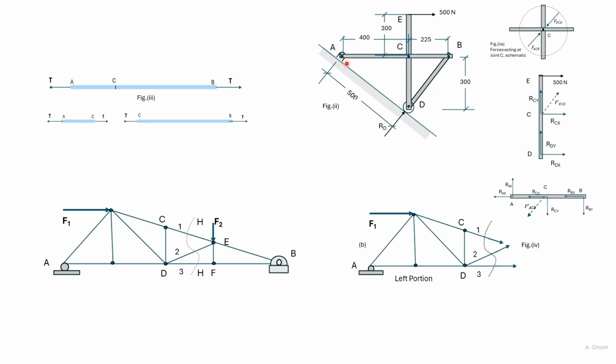Similarly, there will be force acting on the pin due to ACP, and the pin at P will react with an equal and opposite force. So there are two sets of action-reaction forces at pin B. In the nomenclature used in frames, we say that DB will cause an action force and ACP a reaction force. This nomenclature is different from the action-reaction pairs mentioned in Newtonian terms.